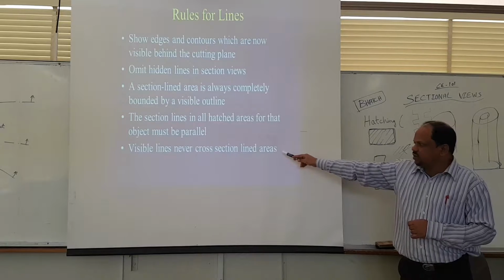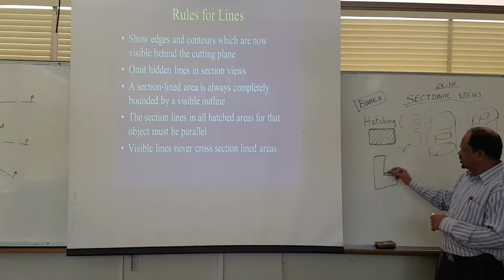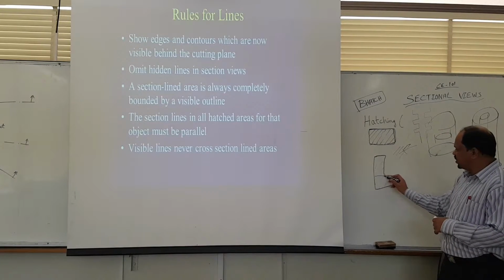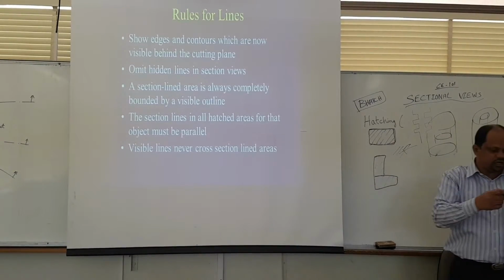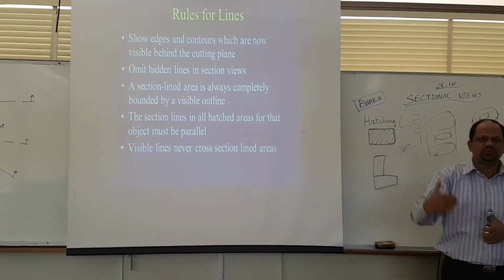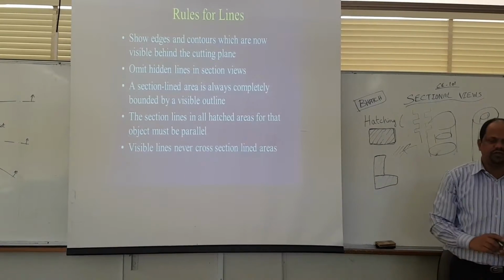Visible lines never cross the sectional area. This is the sectional area. So you cannot have a visible line passing inside it, because after cutting, there is nothing that passes through the sectional area. You cut it, everything.